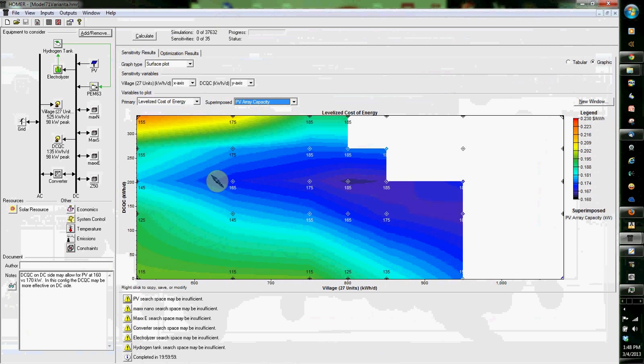So we look at the PV array. Back here, I'm in the 150. I can go as low as 115, but if I want to run a charger, I need to be 125, and 145 if I want to sit up here. But what you don't see here is that because I had more solar available to me, it chose not to use the fuel cell. If I kept it at 125, you would see the fuel cell be a lot more active. But if I allowed the flexibility to go up to 185, then this takes on a new shape. And this really helps you pick and decide how you're going to frame your microgrid.